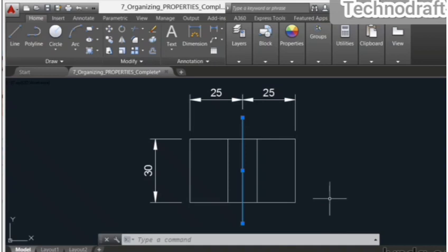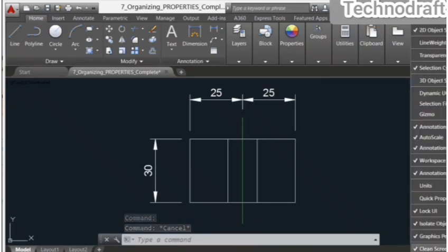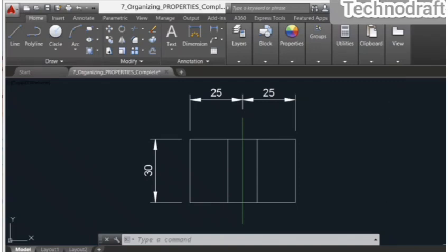If you want to check where your line weight icon is in your status bar, you go down here, click on the 3 little lines and check whether line weight is switched on. Can you see line weight isn't ticked? So if I click that, there are the 3 little lines, then I see my line weight tool in the off view here. If I now click on that, you can see that the line weight is bolder.